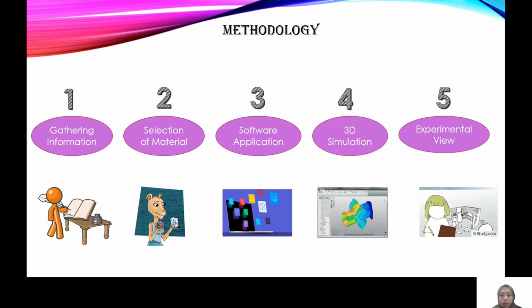Based on research papers, the results show the best flexure properties when layers of carbon are at the exterior. Meanwhile, the highest compressive strength is provided by alternating carbon and glass layers. The intensity of tensile strength occurs towards the stacking sequence. In addition, to provide good correlation with experimental data, an analytical solution must be developed and shown in order to gain maximum strength by allowing optimization of the stacking sequence of the hybrid composite.